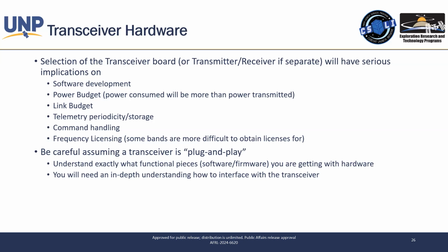And then last, but also very important, is frequency licensing. What frequency does this actually talk on? What does it actually transmit? What is my likelihood of securing a license in this frequency? There are some bands that I discussed at the beginning that are much easier to get licensing for than others. In fact, there are some bands that are basically impossible to get a license for. And you don't want to be stuck in some bureaucratic mess for years and years while your satellite is sitting on a shelf gathering dust because you can't get a license.